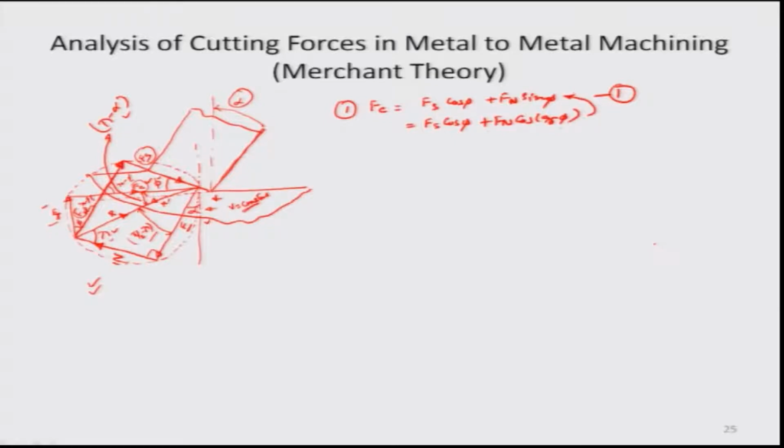I am not going to get into how this works in detail, only this one relationship. From this one relationship it is clear how we are recording Fc in terms of Fs and Fn in terms of the angle. There are many other angular relationships available in this diagram. I am simply going to write down all the force balance equations. So, the second equation then would be Ft equals Fn cos of phi minus Fs sin of phi. Please be very careful about the directions.